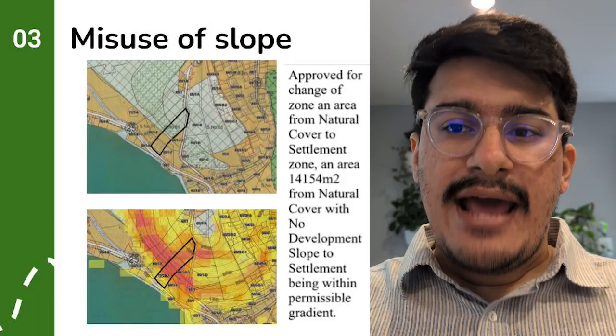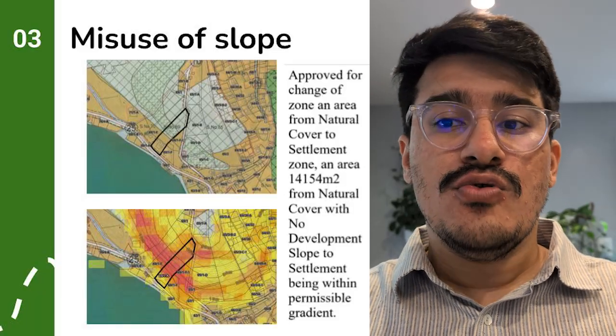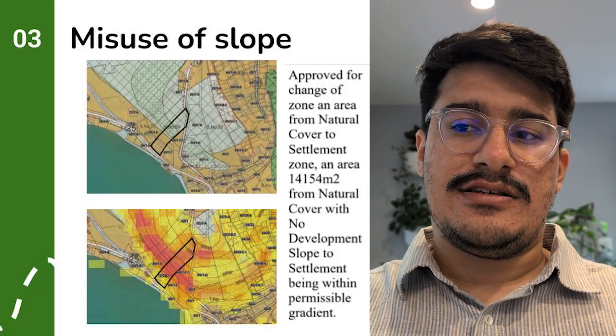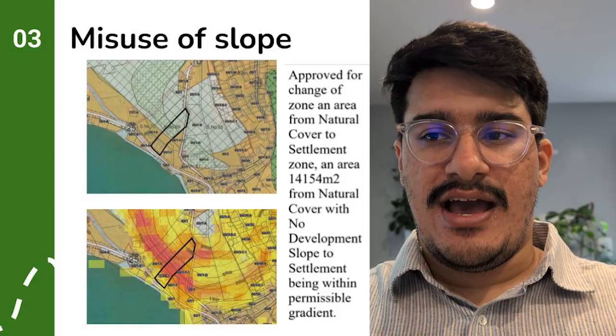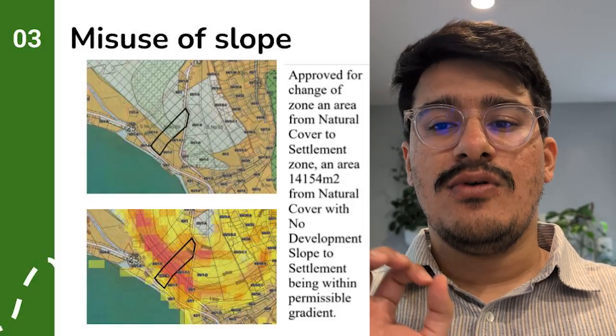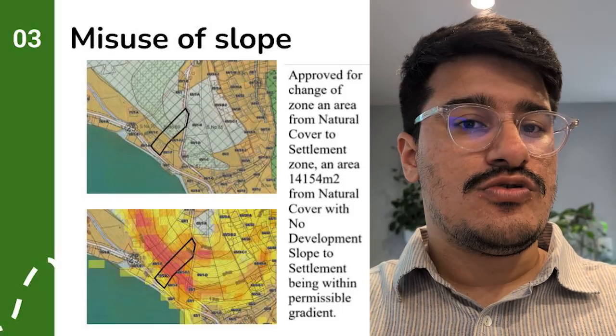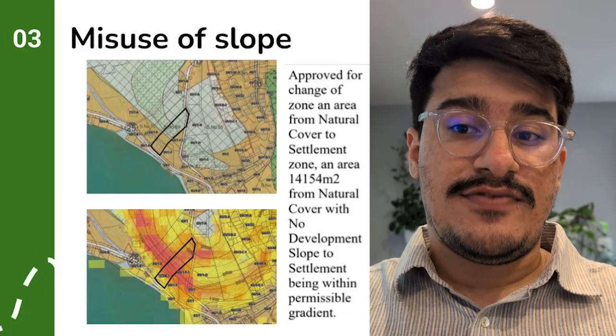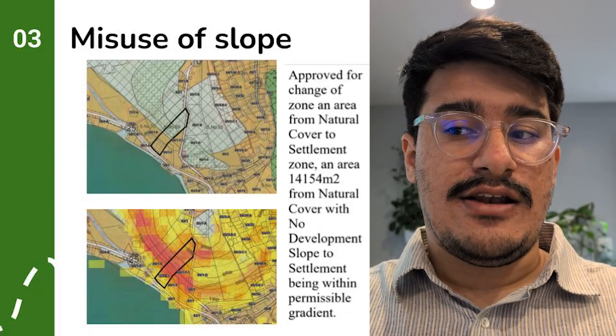A few rare regulations, like New York's, do call something average slope for certain calculations, for example, determining FAR or open space requirements. But even those define it through a formula that forces you to draw multiple sections and take multiple slopes on different parts of the site, and not just the highest and lowest.